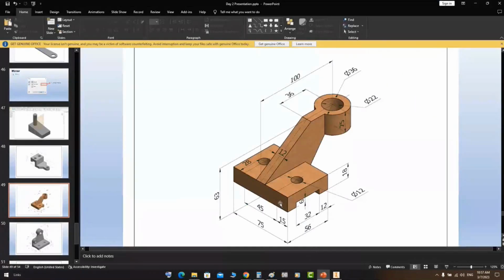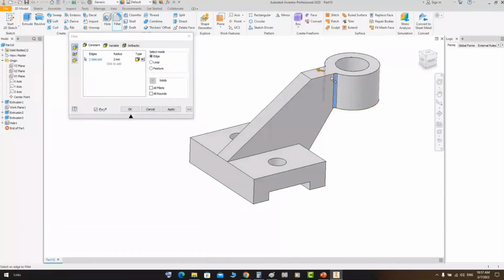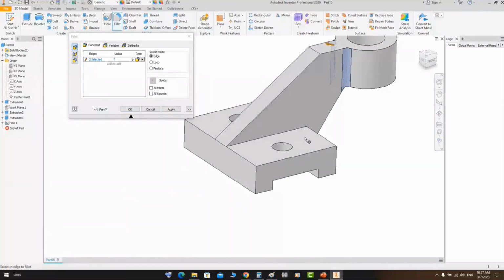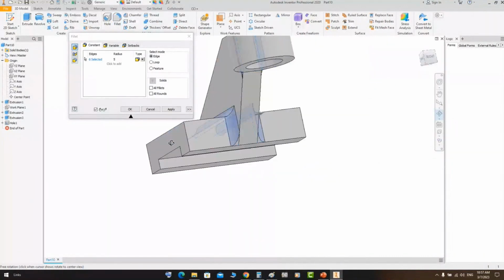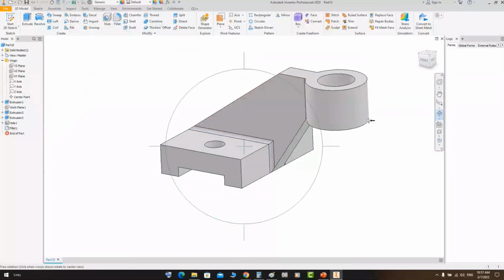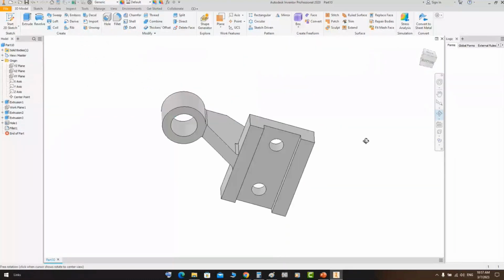Okay, you can add some fillets to this model. Here in this model, no fillets, but you can add some fillets, like adding a fillet on this edge and that one. Let's make it as a 5. Okay, adding a fillet for those sharp corners. So you can add fillets like that to this sharp corner, like that, to make it make a little bit more sense.